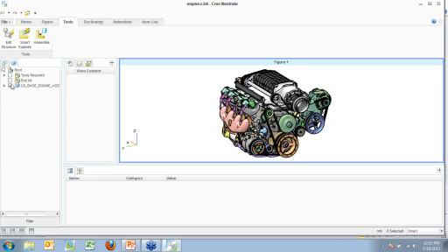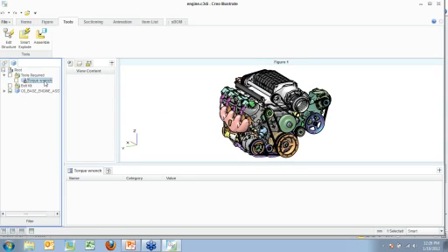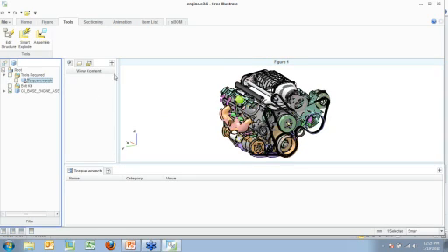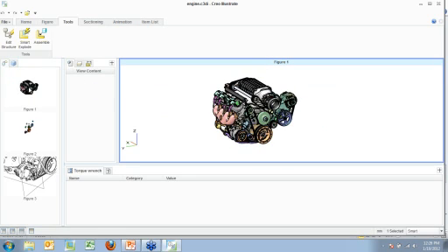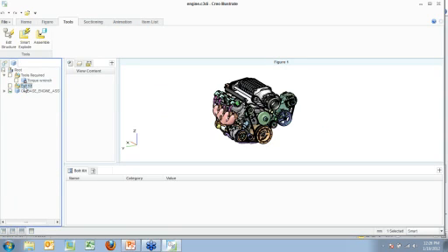So as you can see, I can create bolt kits, the tools that are required. Let's expand this out. The torque wrench, it's right there. It's not in this view. It's being hidden. But I can actually create kits, specify that all of the bolts in the assembly go into one sub-assembly, and that'll create a service BOM for the bolts or any of those components that I wish.